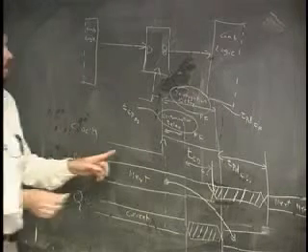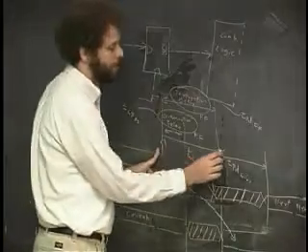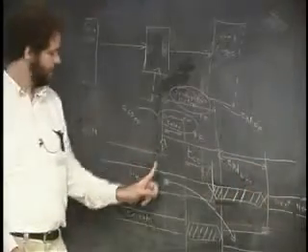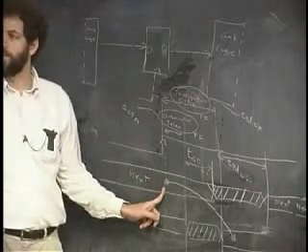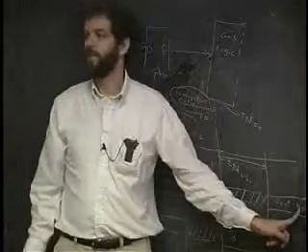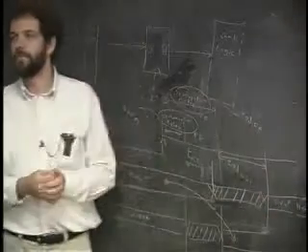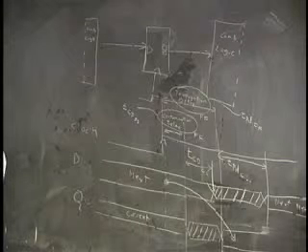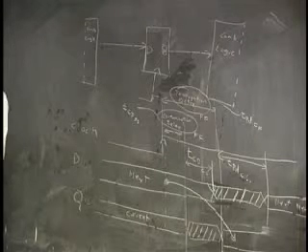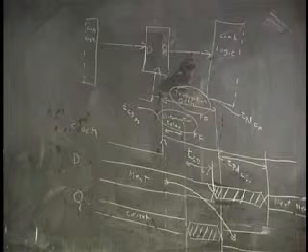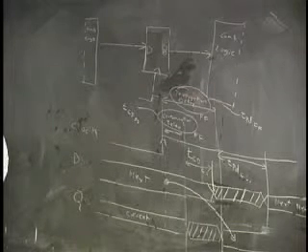We're not going to clock it until sometime over here. We clocked it here when the output of combinational logic was good, and we're not going to clock it again until over here, after all the garbage has passed through. And if we did clock it when the garbage was going through, then the machine would jump into a random state, and you'd get the blue screen of death, and Windows would crash and all that. We're going to talk a lot about how to prevent that from happening.